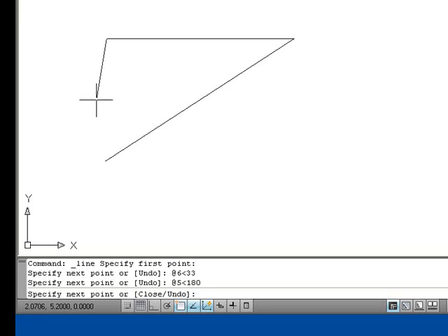Once again, you use the @ sign to tell AutoCAD that you want to indicate a point location relative to the last point. The distance and angle are specified in the same way as the first line segment, using the less than sign to indicate that an angle value follows. In this case, you use the number 180 for 180 degrees.